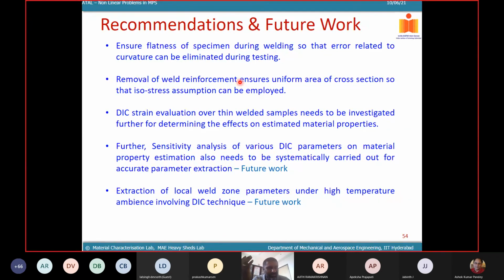We put the specimen on an exciter and lock the camera and the exciter so that we capture the out-of-plane displacement under vibration, especially for mode shape measurements. People have used DIC for large blade structures and flap structures. So there are a lot of vibration applications, especially for mode shape.